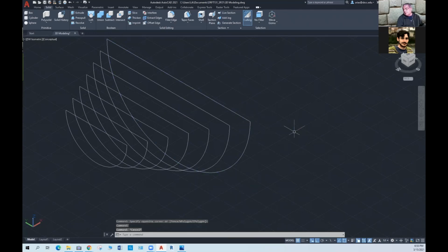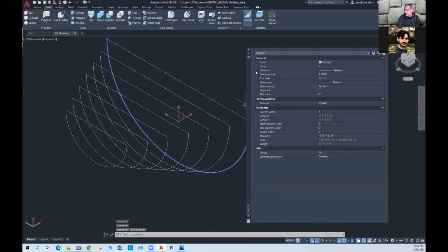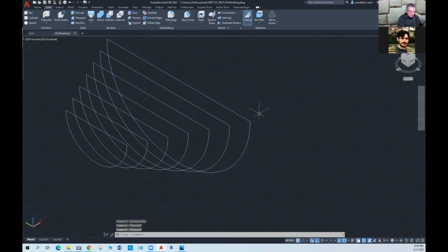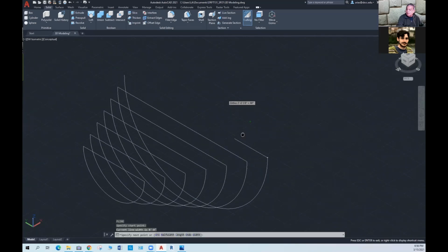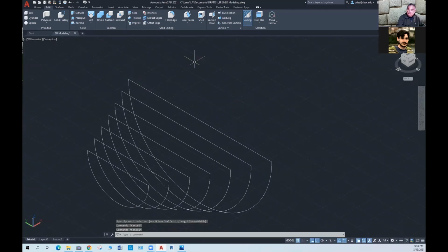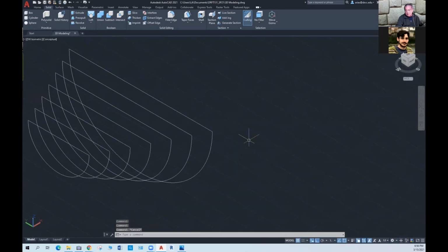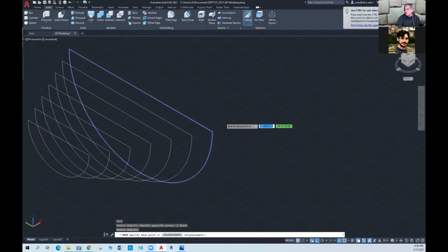So this is typical. It's typical that we may have a hard time trying to join an object to make it a polyline or not. Let's see what this object is. It's a polyline. And let's delete this again and do another polyline, right? PE for polyline. Select that point and that other point. Now we're going to do PE. Select polyline, join. It's still not. See, so that's a difficult thing to do.